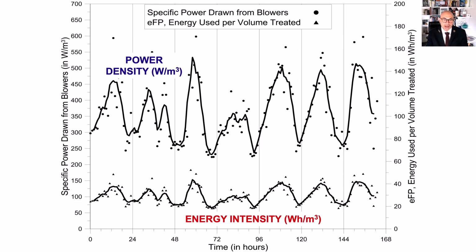So integrating these two times the tariff structure over a period of a month gives you the monthly energy cost. If you only look at the energy consumption in, say, kilowatt hour in a month, it's probably half of your power bill. The other half is the power demand charge, because this is three-phase, usually medium tension power that requires a lot more, a lot costlier operation in order to supply it, and it costs a lot more on the end of the demand, to rephase it and so on and so forth.